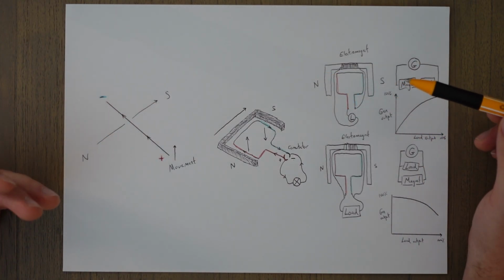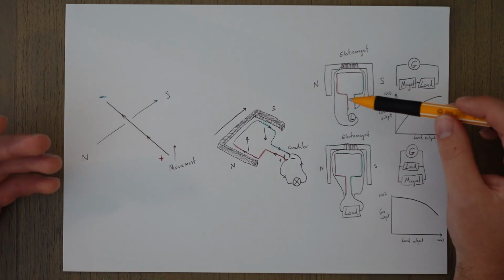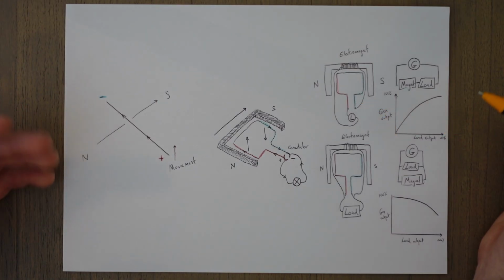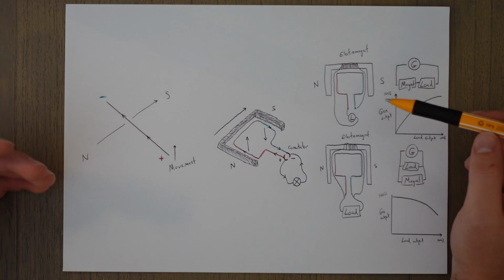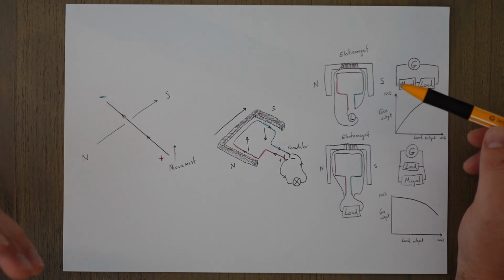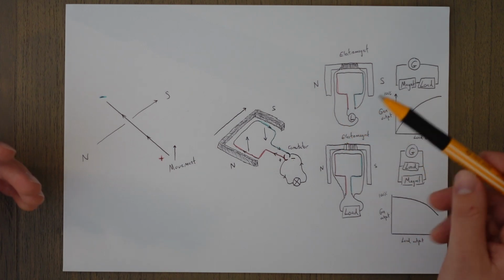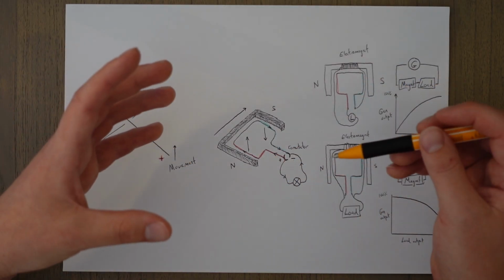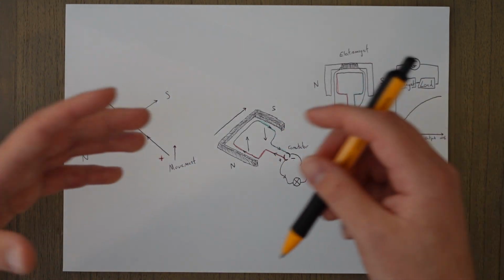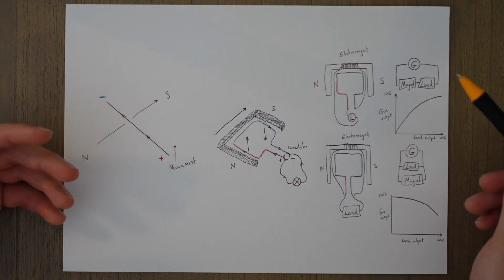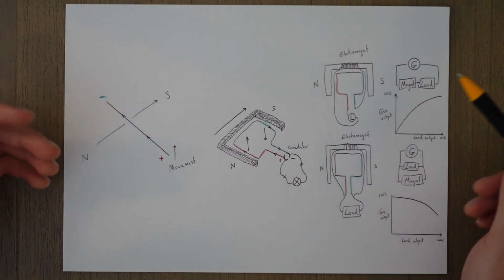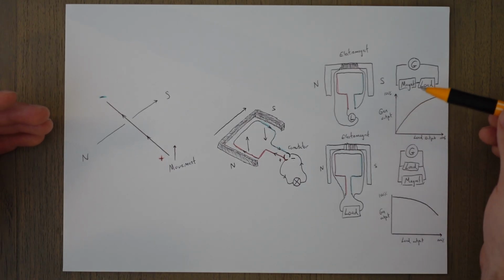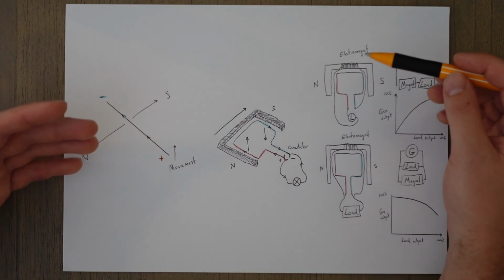Like with a motor, we can connect the stator electromagnet in series or in parallel with the output loop of wire and the output voltage and current. For a series setup, we use a high resistance wire for the stator, much like in a motor, to control current flow. And in this setup, if we rotate the rotor faster to generate a higher current, then the current in the stator also increases, and that means a stronger magnetic field, and then it builds and builds, and it means more electricity flow the faster the rotor of the generator spins, and it grows exponentially like that. So you've got a higher load output and a higher voltage and current in the electromagnet as well.